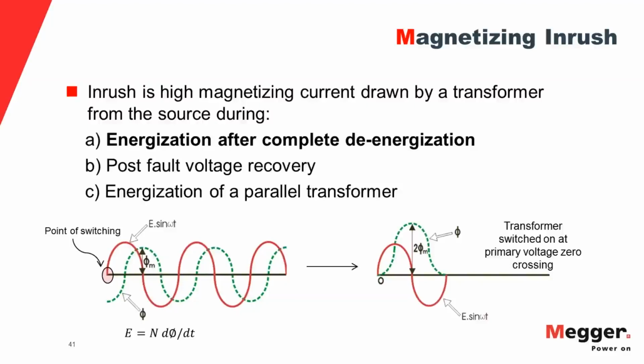So with this law, in theory, we will see that my voltage will be in 90-degree shift with my flux. And if you remember, I said that the breaker is closed at the zero crossing of the voltage. So this would tell in theory that my flux should be on the negative maximum, which cannot happen because I've said that I've completely de-energized the core.